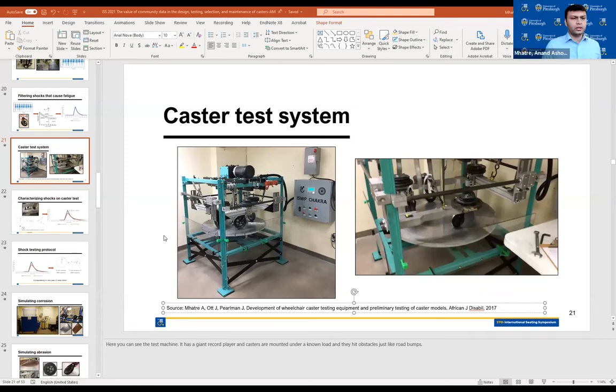Jack, can I add one thing here? So, it's a good question. Do we need to change the lab test? I don't think we need to change the lab test at the moment. The big reason is that we did the tilt-in-space wheelchair testing without understanding how the load is on the tilt-in-space wheelchair. We did the testing under a standard load, under standard conditions, but it may not be the same way it is mounted on a tilt-in-space chair. So we need to get that data and integrate it into the testing, and understand how that loading is before we make a decision on whether we should change the lab test. We are getting promising results here, but I think some data still needs to be there as backup for the test method. Then we can conduct that test and find out whether we need to change the lab test.